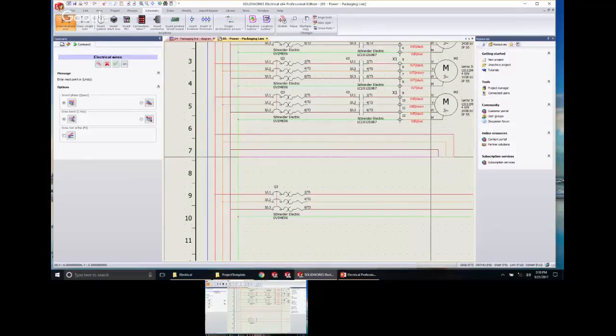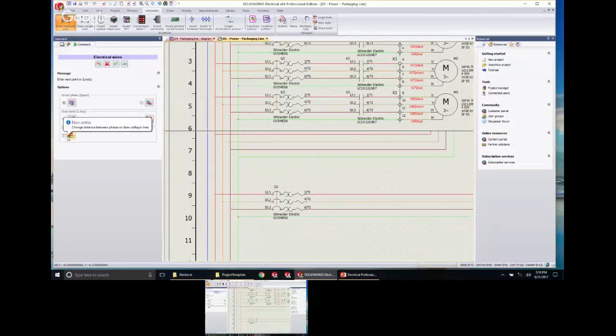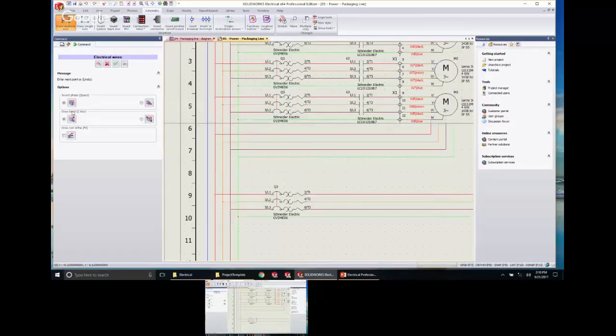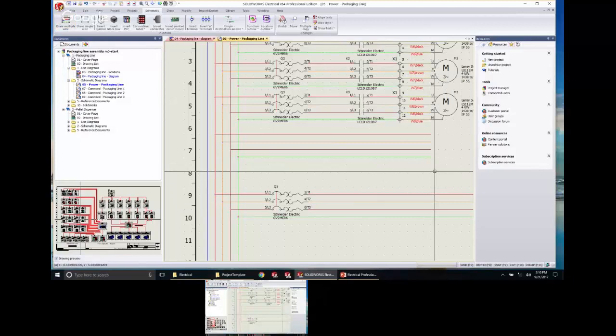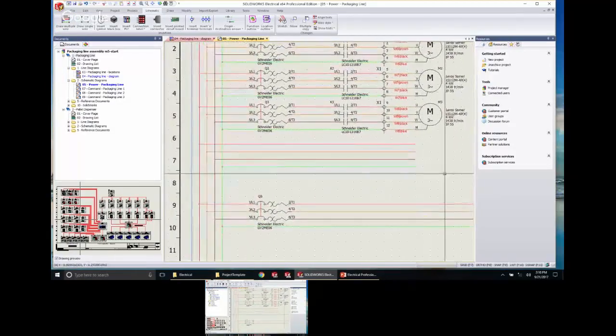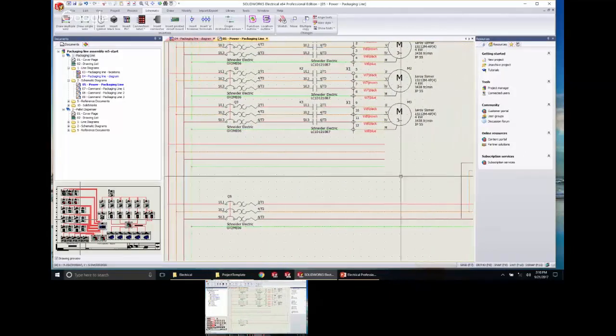I'm just going to left click, and then a trick, another keyboard shortcut. So notice when you left click, it automatically starts doing, I'm going to 90. Here over on the left, we can invert the phases, do different bends, do non-ortho if you're going to some kind of connector, or you can use space to invert. Again, keyboard shortcuts here. So another trick of, instead of going up to the left and hitting the green check, just hit your right mouse button, and it'll end the command and accept it. So there's my new wires here.